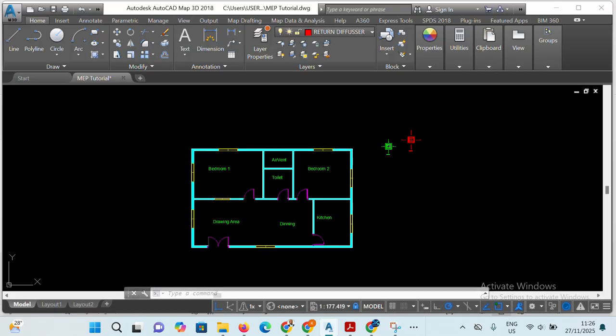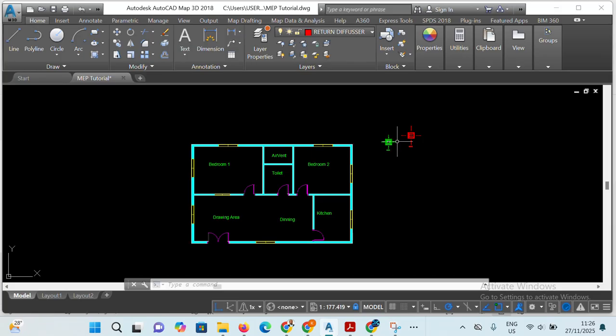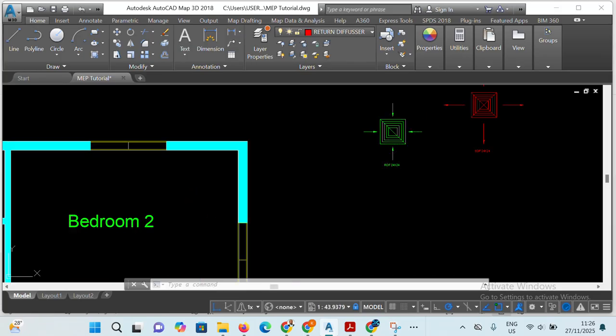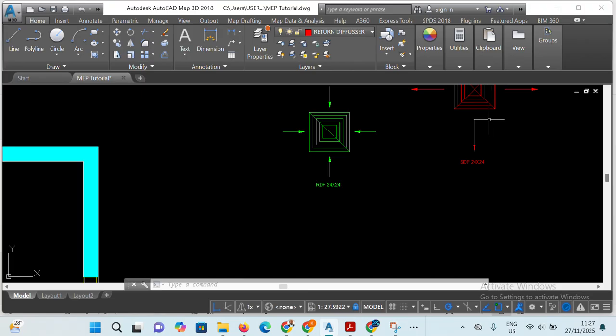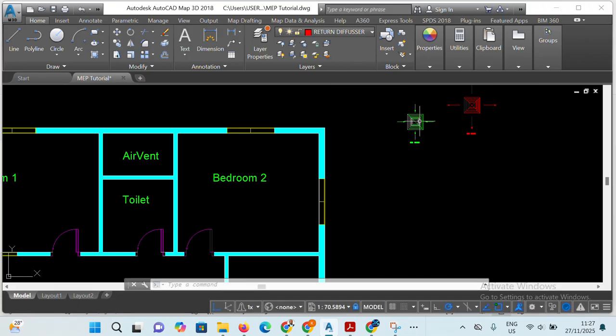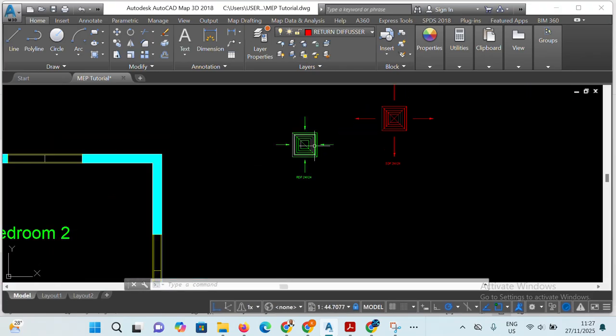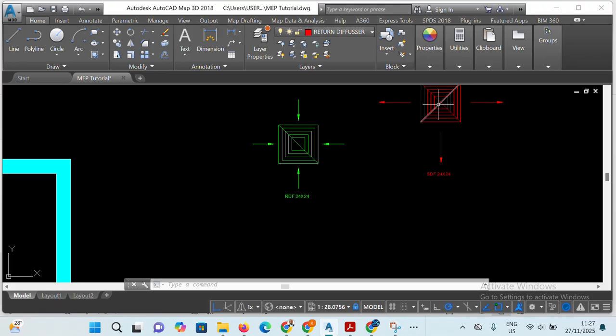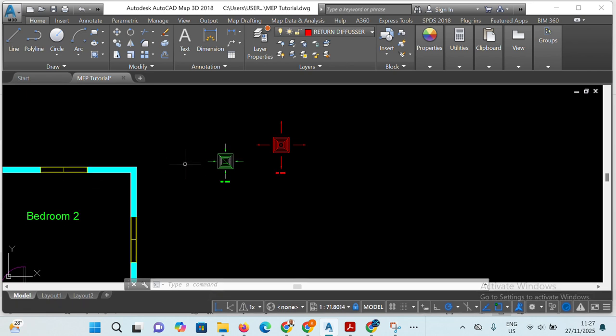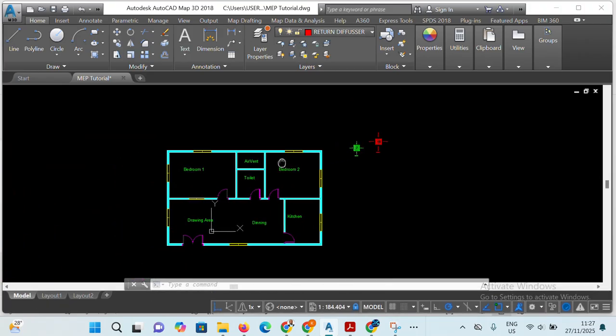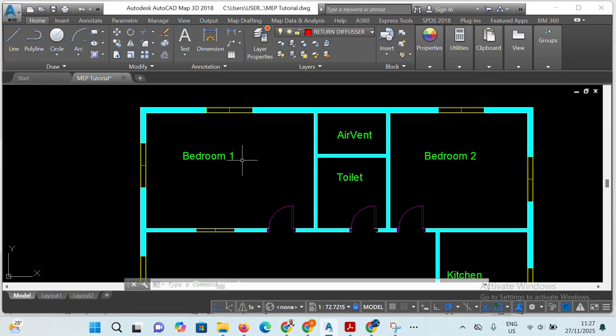Good day. Today we are going to continue from where we stopped in the design of air terminal devices, sizing of air terminal devices, as shown in the previous calculations. This is a return diffuser and this is a supply diffuser as shown in the diagram. Don't forget, the return diffuser has only one diagonal while the supply has double diagonal and the arrow is pointing outwards. Today we are going to look at how to place these air terminal devices in a room.